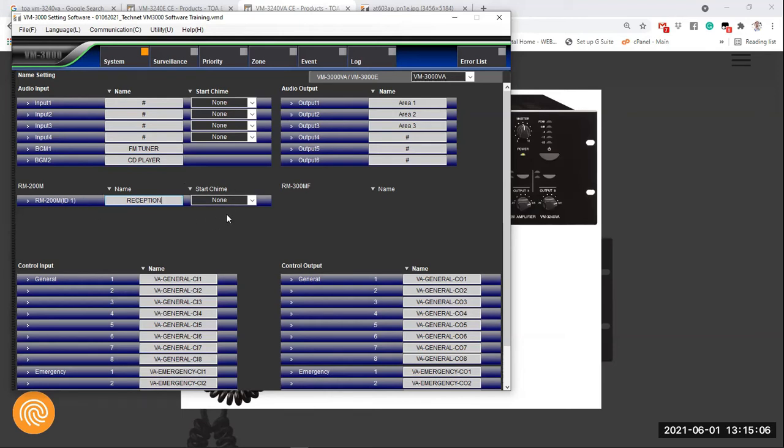And over here, I need you to pay special attention. Under the microphone tab, you can change the name, right? By default, the software will not allocate a single tone, a 2-tone, a 4-tone, or a gong to your microphone. That ding, ding, ding, ding, you need to choose here.